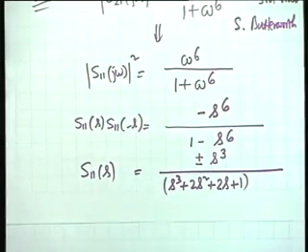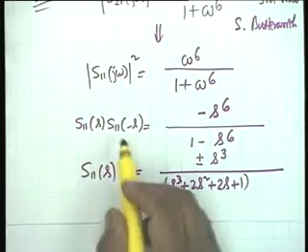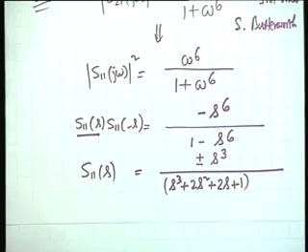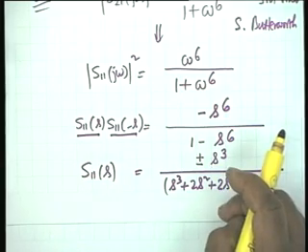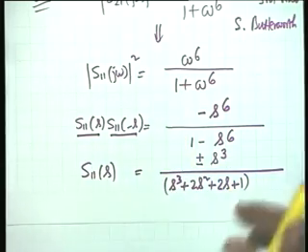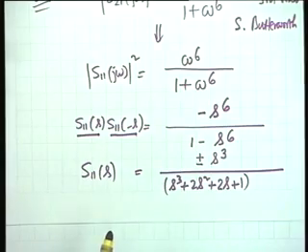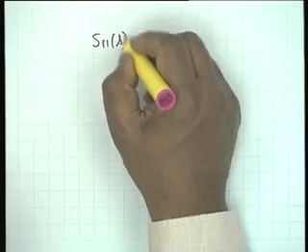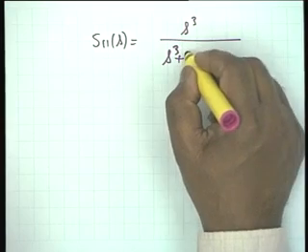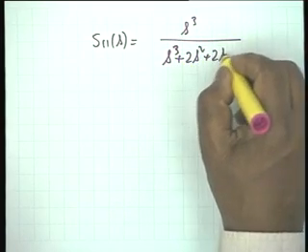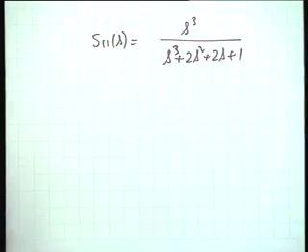What should we do? So we can take s also s squared. No, we cannot, because one is S11(s), the other is S11(-s). If you take plus s cubed here, you have to be fair to S11(-s), you must give that minus s cubed. Alright, you cannot take any power of s here. Alright, so let us take S11 of s as equal to plus s cubed divided by s cubed plus 2s squared plus 2s plus 1.